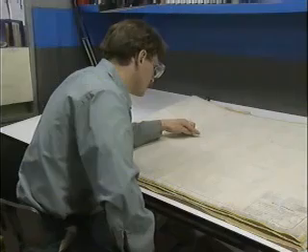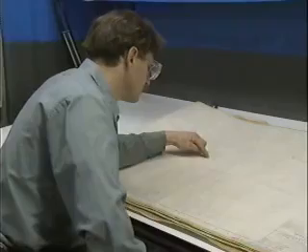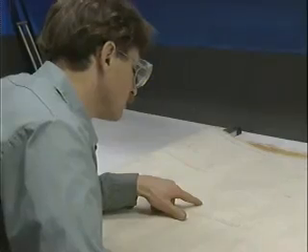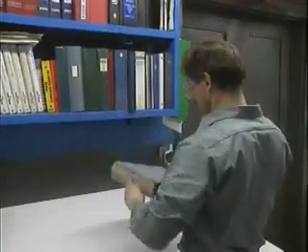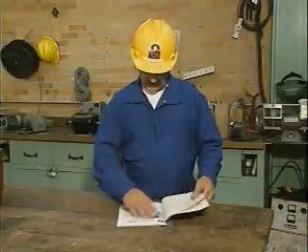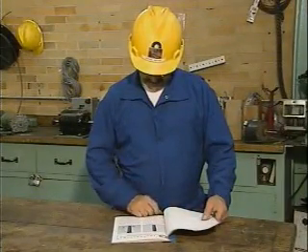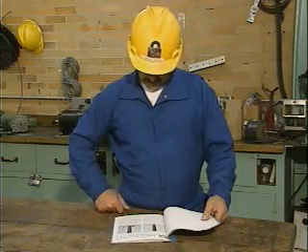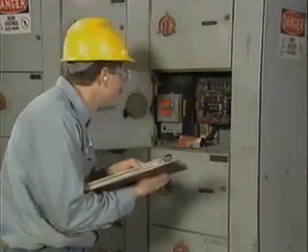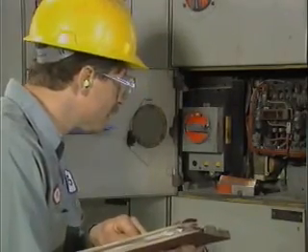Schematic diagrams can help you identify the controller's components and how they are electrically connected. Using a schematic diagram to trace the current paths through the controller is one way to determine how the controller is supposed to work. Other sources of information include system description manuals and technical manuals. System description manuals typically describe what a system is, what components it contains, how the system and its components usually operate, and where each part of the system is located. And manufacturers sometimes supply technical manuals for their motor controllers. These manuals describe normal controller operation and provide other pertinent information.